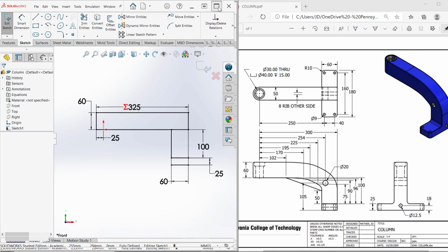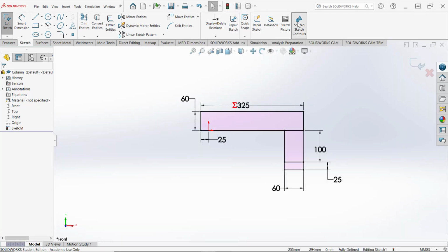on the visibility of the shaded contours and so we see that we have 3 closed areas. I usually work with that turned off, but you can turn that shaded contours on or off. And I change the colors. Your colors would probably be a light blue rather than this color.